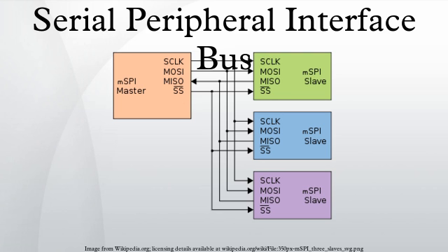Daisy chain SPI configuration. Some products with SPI bus are designed to be capable of being connected in a daisy chain configuration, the first slave output being connected to the second slave input, etc. The SPI port of each slave is designed to send out during the second group of clock pulses an exact copy of what it received during the first group of clock pulses.